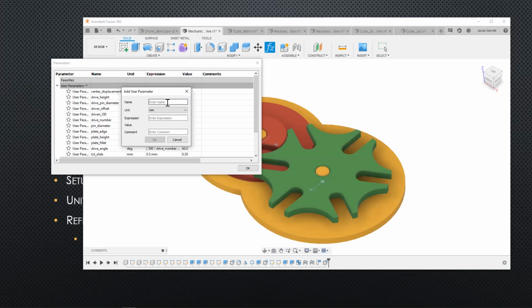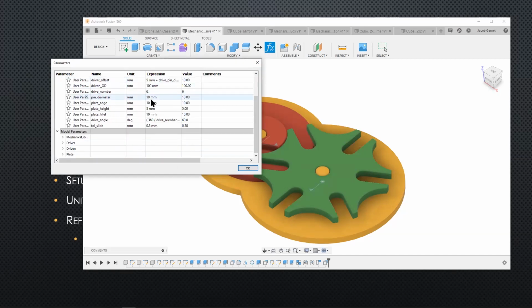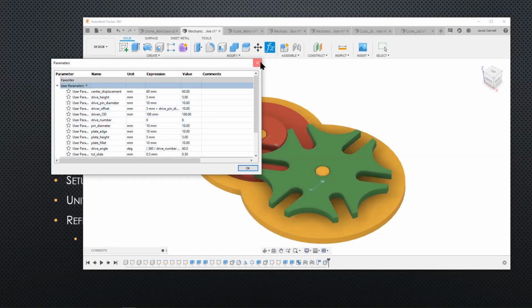What you can do is type equivalent types of units. So let's say test. So parameter name is test, units is millimeters. I can put this in as 1 inch. I can include the units in another type of unit, and it will just convert it into that size. But I can't do like 1 meter cubed. No, because meter cubes and millimeters don't have a conversion. So just remember that if you want an angle, you're going to have to tell it that you want an angle.